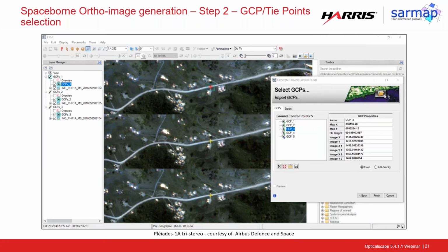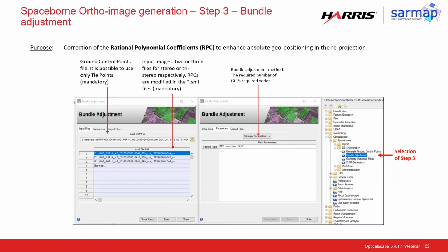And this is an example of why we can't directly reproject the points on the multispectral images. As you can see, the ground sampling distance is quite different, and also the rational polynomial coefficients may have a different calibration. Finally, you can correct the rational polynomial coefficients with 4 different algorithms that we provide. Each one of them requires a different number of ground control points. It is specified in the online help how many are needed for what type of correction.